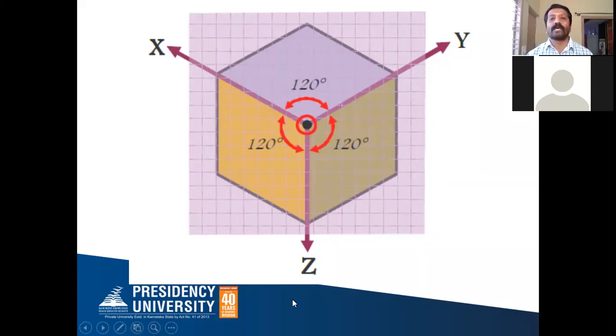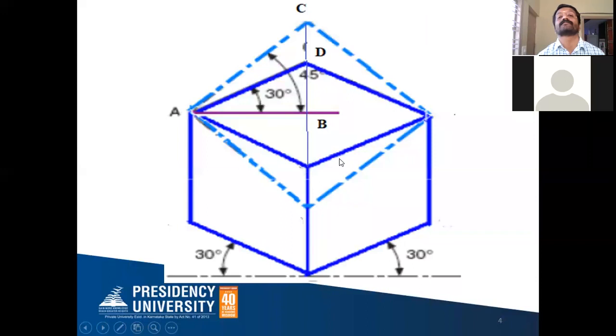So whatever the dimension that you have to take, and you have to draw the projection to complete the isometric projection, we need to draw on these three axes only, either on the 30 degree lines like this on either side, or else on the vertical line. So all of you understood this. So if I draw a horizontal line here, 120 is there, total horizontal line is 180. 180 minus 120, 60. 60 by 2 means on either side, here 30 degrees, here 30 degrees you are going to get like this. So here clearly I have given it so that you can easily understand.